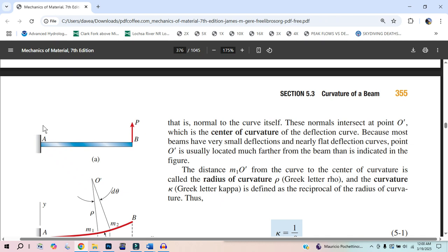Like in statics, which is a whole class, it can be complicated just to say, if I put a force here, a distance away, at the wall I'm going to have a moment. Just put yourself at the wall. You unbolt this thing, and you have to hold this cantilever with two hands, and someone pushes up on it and says, hold it still. You know what I mean? What would you have to do to hold it still? You would actually have to put a downward force.